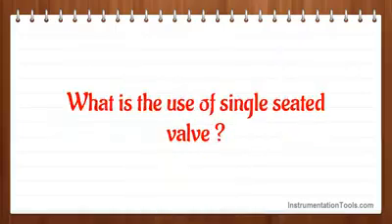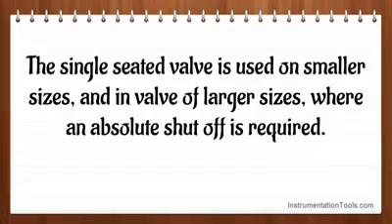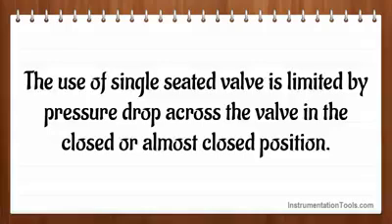What is the use of single-seated valve? The single-seated valve is used on smaller sizes and in valves of larger sizes where an absolute shut-off is required. The use of single-seated valve is limited by pressure drop across the valve in the closed or almost closed position.